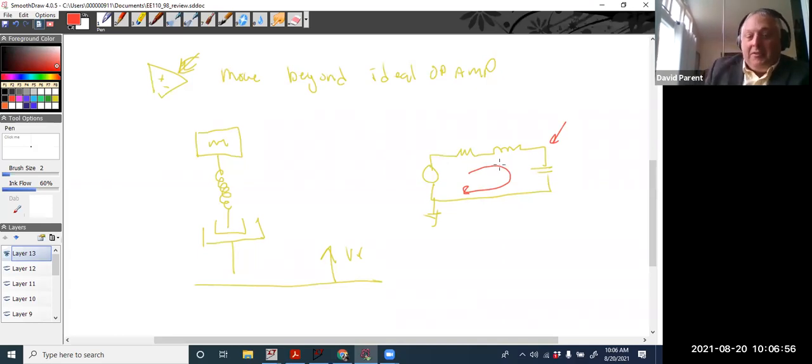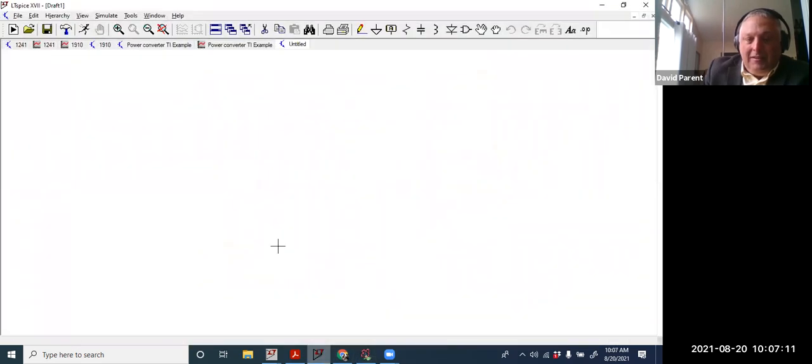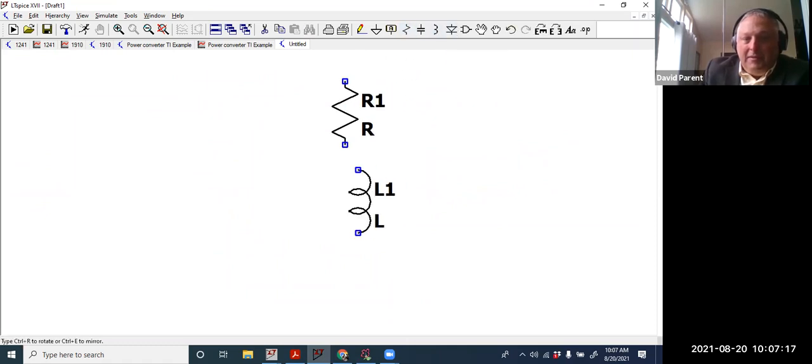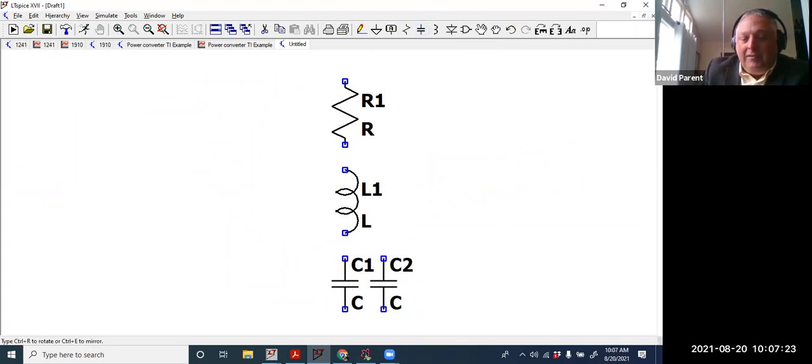We can do a Bode plot of how this would react, right? So all of these things can be done with a circuit. And so I can simulate a mass, spring, and damper in LTspice, right? Here's my damper. Here's my inductor. Here's my capacitor, that's a mass. Whatever the mass is, I just convert it to farads. Whatever the spring coefficient is, I convert that to henrys, and whatever the damper is, I convert that into resistance, right?